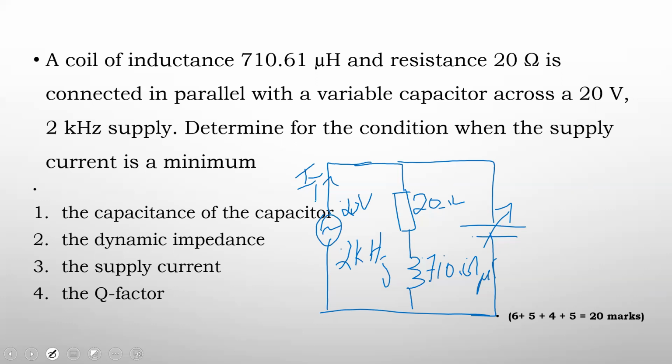Okay. So you're saying the next step is to find the impedance? Go again, let me hear the step. The next step is to find the impedance in the coil. When we find the impedance in the coil, we can use the resonance frequency equation and transpose it to find the capacitor.